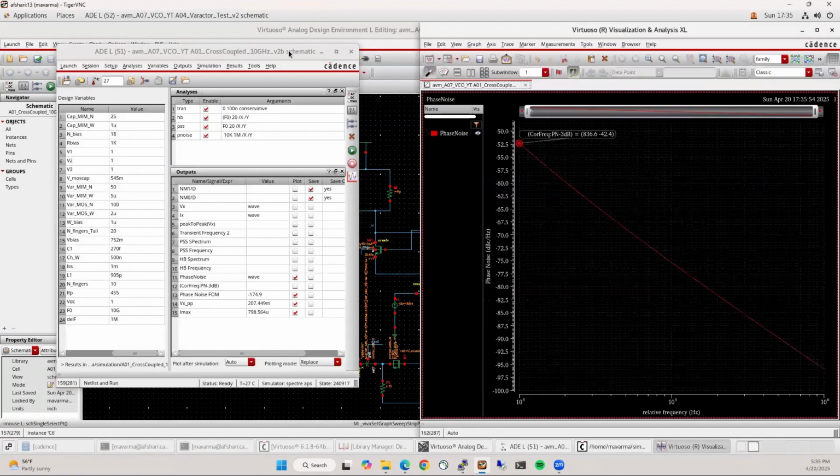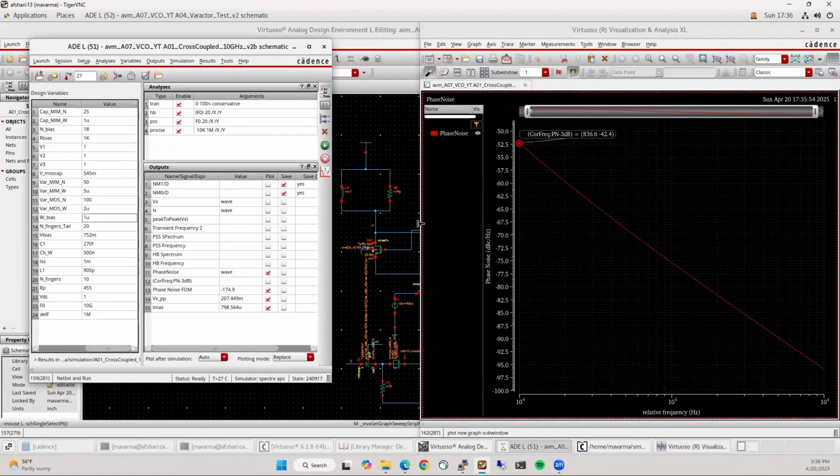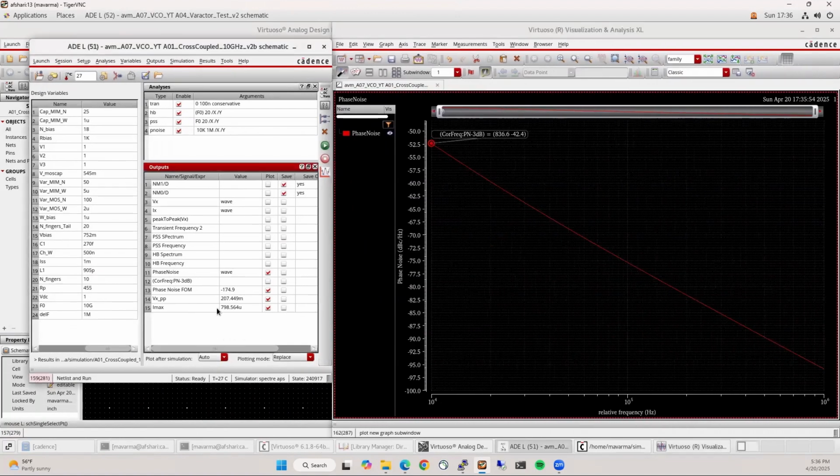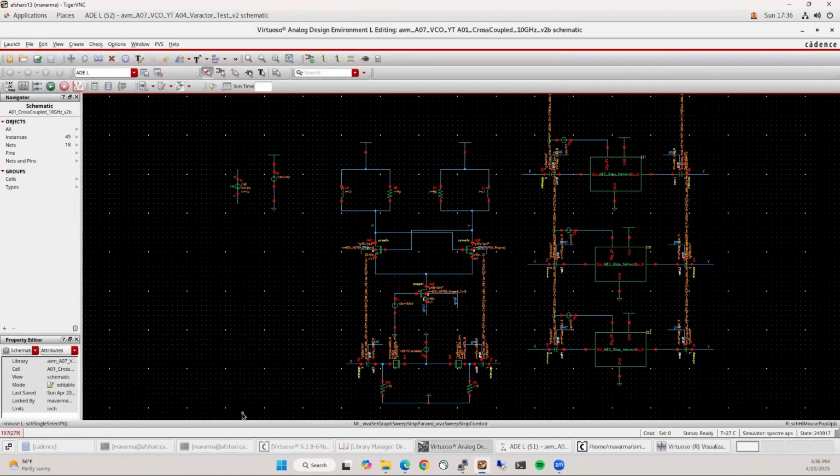Putting this to the side. All right, so you can see the form dropped, right? Swing also dropped, both voltage and current. And that's because the Q of this tank now is much lower, because earlier we had an ideal capacitance, whereas now these capacitances all have some loss, right?